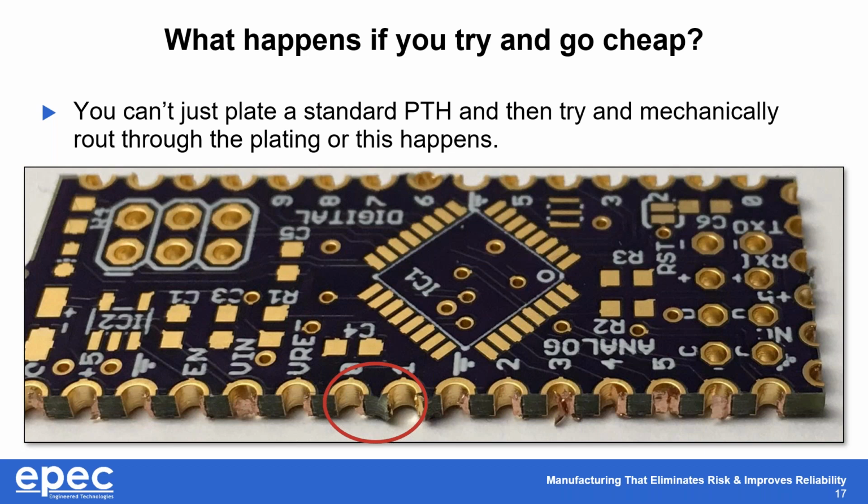What ends up happening is that many fabricators will come up with some sort of a tool. They'll take pins and say, okay, we're going to use those plated through holes and put them down on pins. And all that really does is create significant damage inside of those plated through holes. So the real key is to have some non-plated through holes in here, or to use double-sided tape, which creates its own challenges. But at the end of the day, nine times out of 10, a customer is going to get what they don't want. And then when they identify what it is that they want, and the fabricator realizes what steps are going to be required to get it, it creates more cost for the customer.